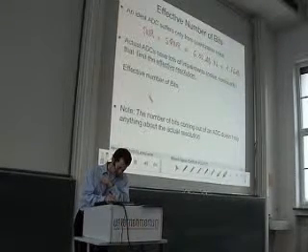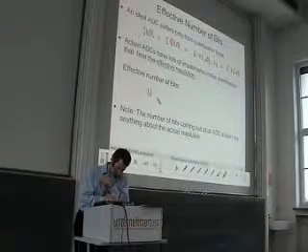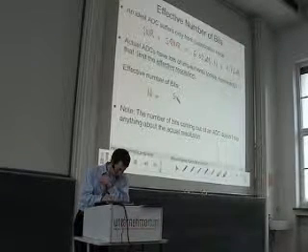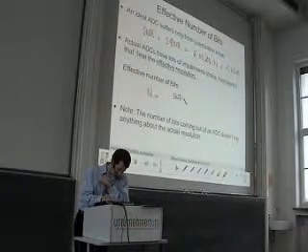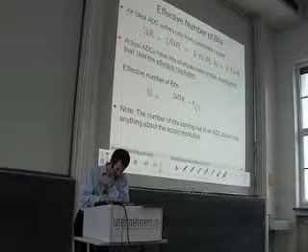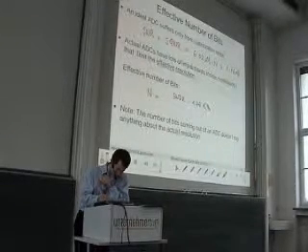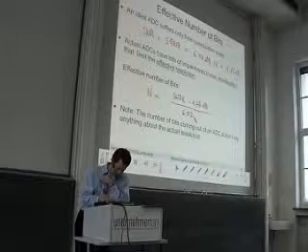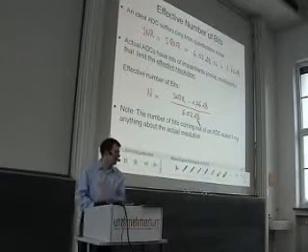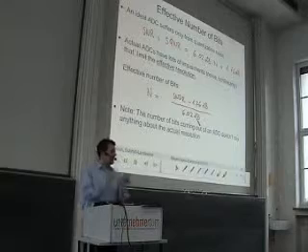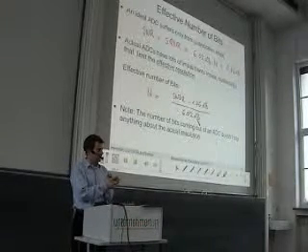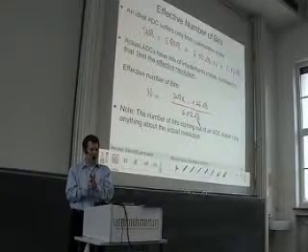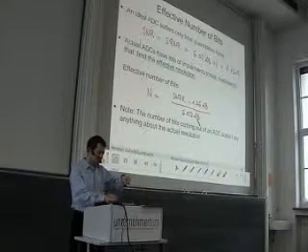So we say n is given by signal-to-noise and usually distortion ratio minus 1.76 dB divided by 6.02 dB. This means an ideal ADC that has the same signal-to-noise ratio than the one we have measured would have n bits.